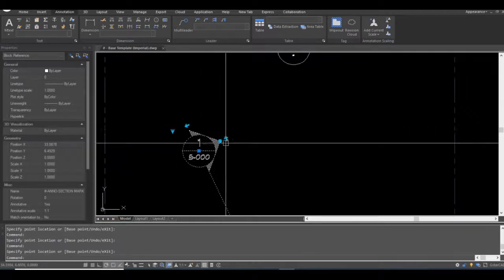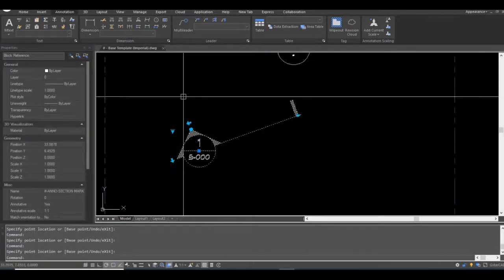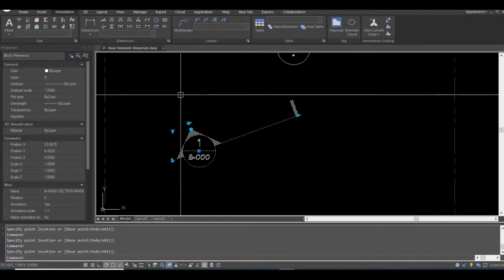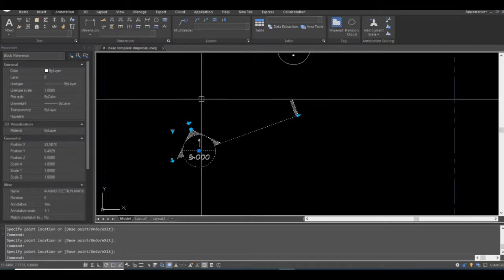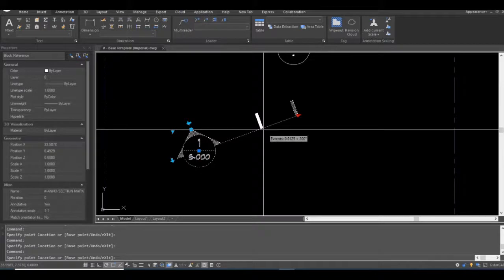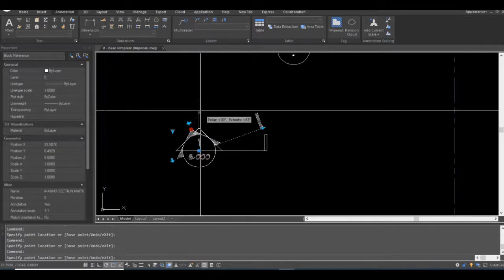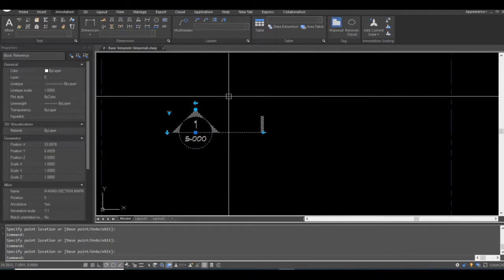No, quite honestly, this is working perfectly. So I think maybe in GstarCAD, if you heavily modify a block, the existing blocks might not take to the changes perfectly. But as you can see, as long as I insert a fresh version of the block, it's working perfectly fine.